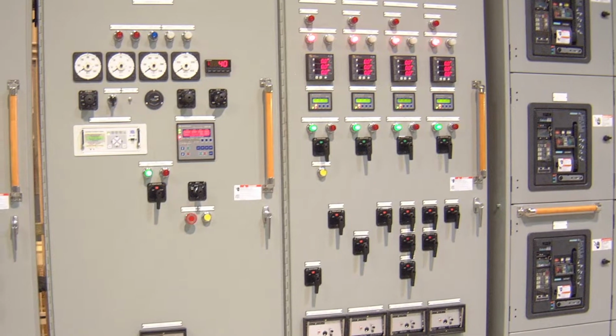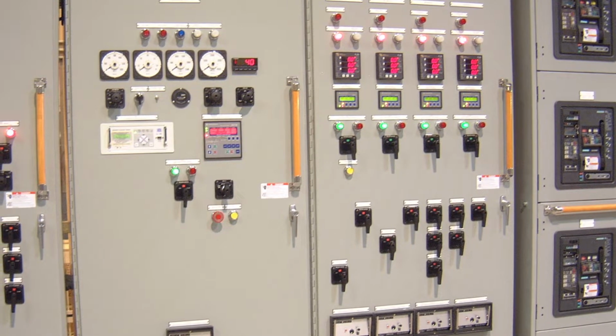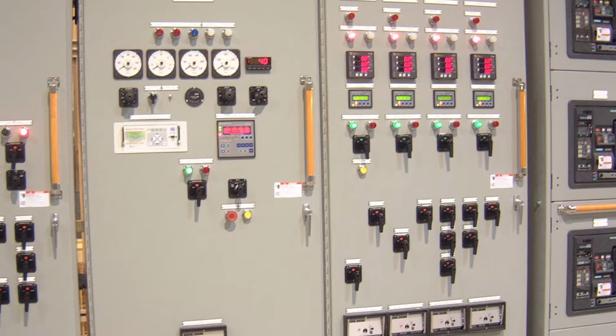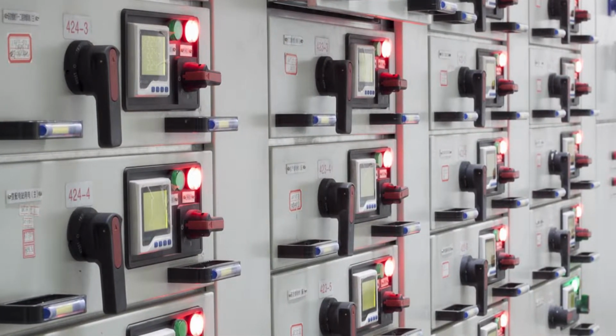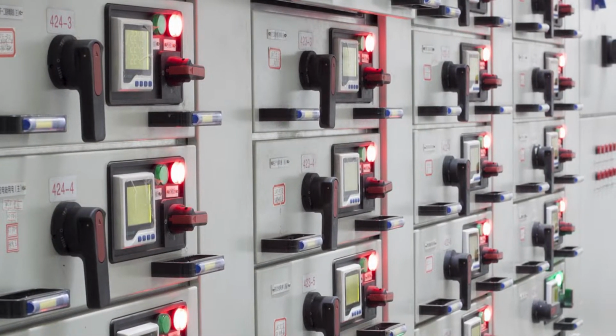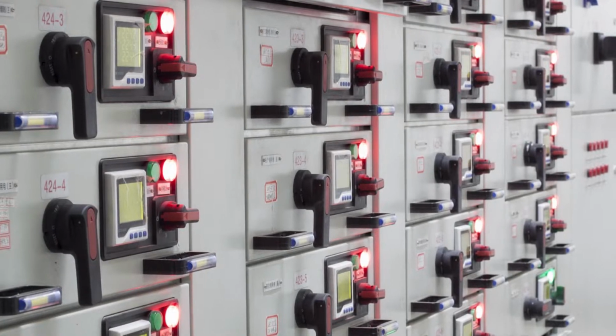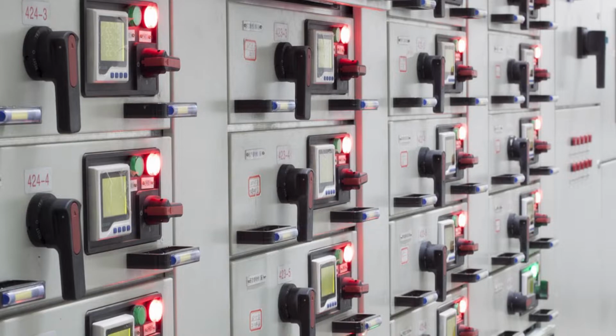One way to reduce electricity charges is to optimize the plant power factor. This can be done by installing capacitors, which reduce the amount of apparent wasted energy and the subsequent kVAR charges. It is common for capacitors to be placed both individually and in large centralized units. There are advantages to both options. Contacting your local power provider and retailers will help you identify which application is best for your facility.